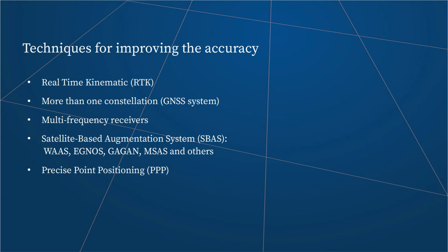The receiver records raw measurements. These are pseudo ranges and carrier phases from each satellite. And then, when they have precise orbits and precise clock corrections, they are able to calculate a much more accurate position. And this method proved itself to be very good. So the companies decided to use it in real time.